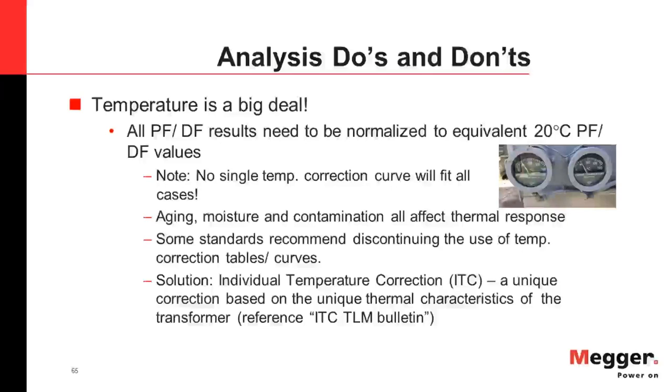Aging, moisture, contamination, they are all going to have an effect on how a dielectric thermally responds. So temperature correction curves in use for decades are rendered invalid, and they themselves could complicate your analysis by introducing error. In fact, some standards recommend discontinuing the use of these correction tables and curves altogether. There's an IEEE standard that has that specific language.